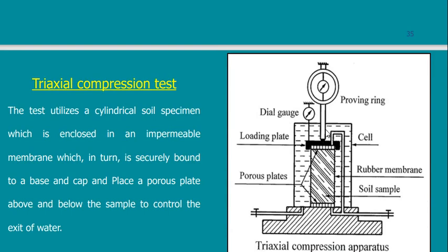From what you have seen before, how do you expect the shape of the failure? How will this sample be sheared? Do you remember? What will happen really is that this sample will start at the beginning to bulge a little bit, because you are increasing the stresses here, and the stresses want to go radially. Then when I reach a certain limit, I will find that the sample is going to be sheared in a plane that has an angle.